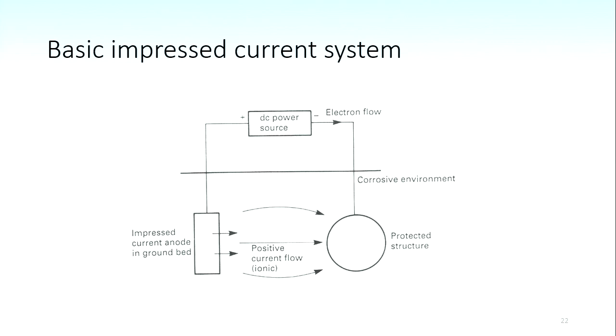That's well, we're going to do that later on. We're going to look at the current calculations. But you're right, the current that you require relates to the surface area, and that relates back through to your number of anodes and power supplies. So you can scale it up.